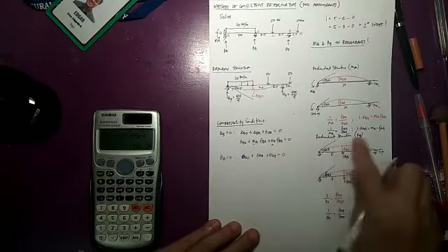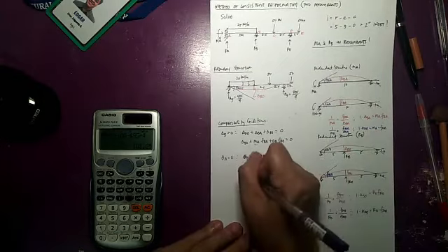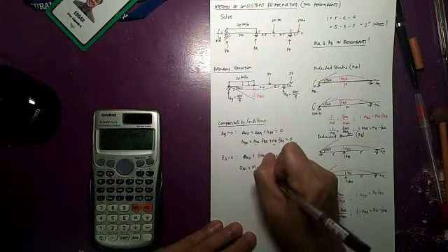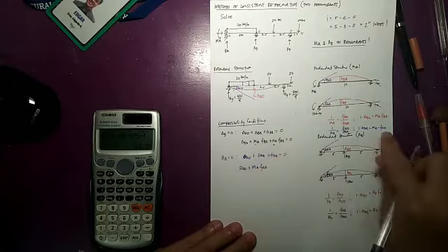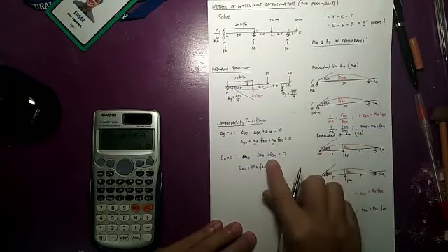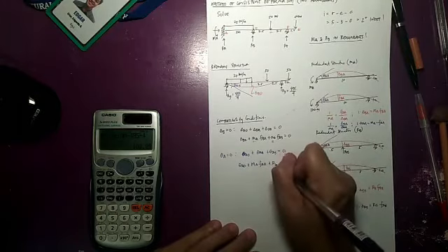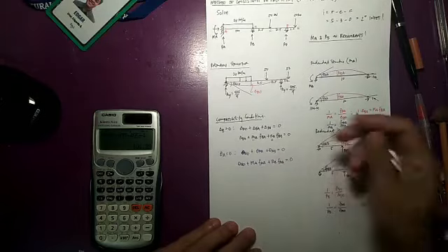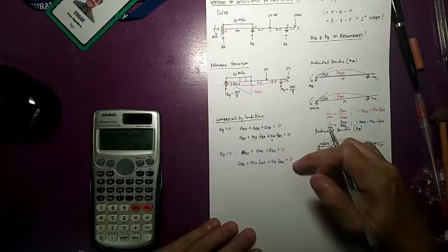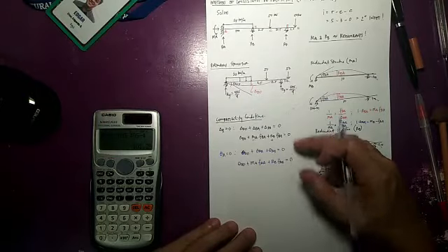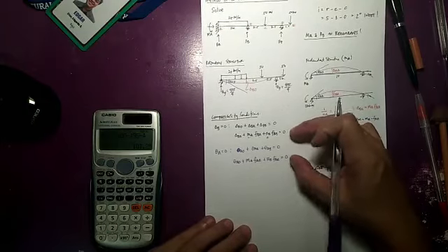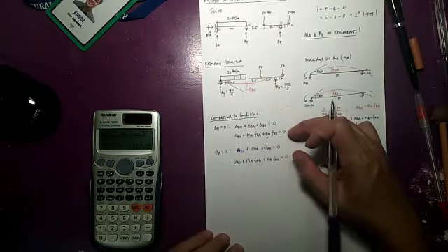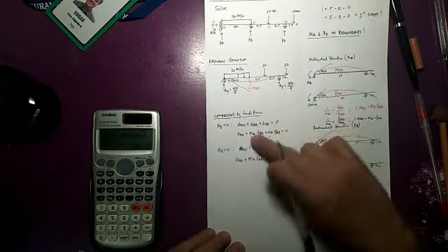But what is theta AA? Theta AA is equal to this. Substituting, we have MA times FAA plus theta AB, which is RB times FAB, should be equal to 0. This would be our second equation of compatibility. As you can see, we have two equations with two unknowns, MA and RB. By solving simultaneous equations from these compatibility equations, we could solve for MA and RB.